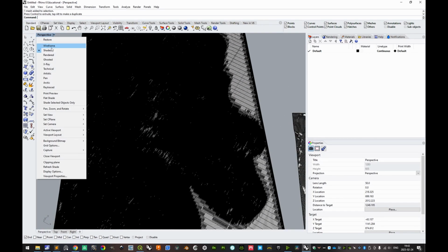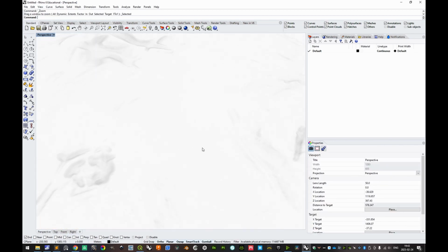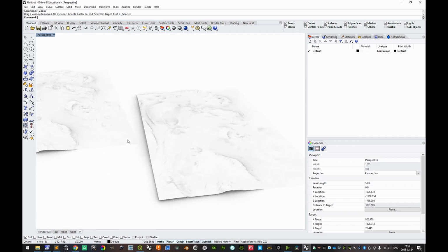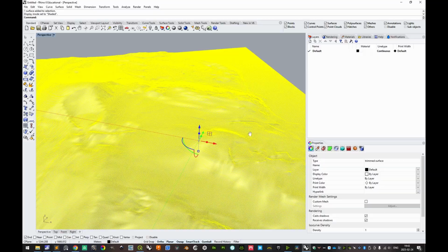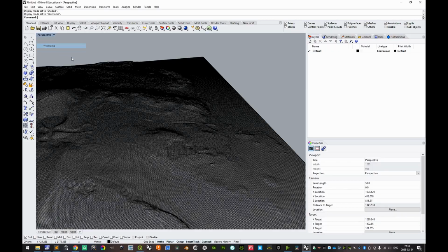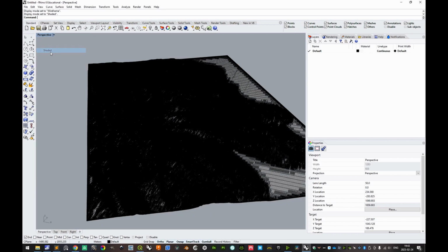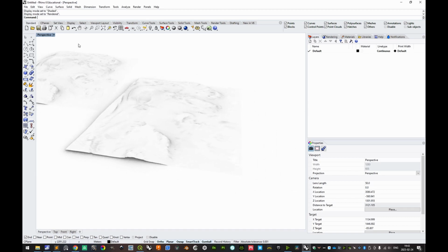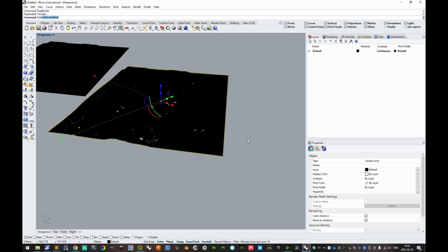And now we are in shaded view mode. Let's go to rendered view mode and zoom to selected to orbit around it. This looks good enough. Very good. So this is only to confirm that we have generated a BREP surface, as we can see here with the control curves, or perhaps more clearly with the wireframe where there is no implicit render mesh. And from that we have created our mesh.